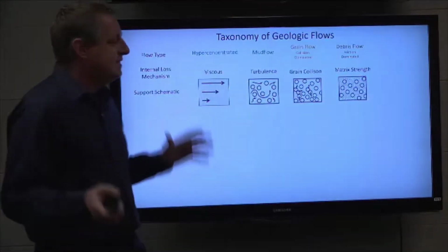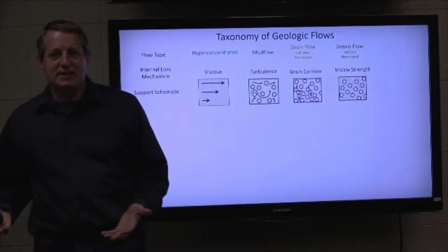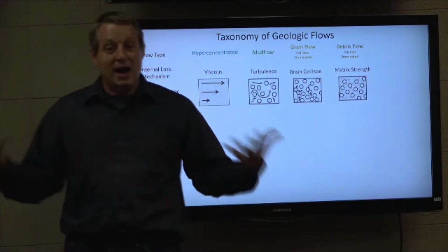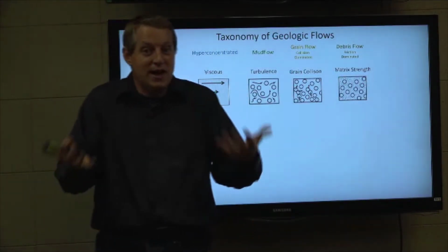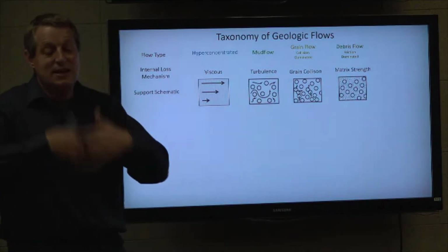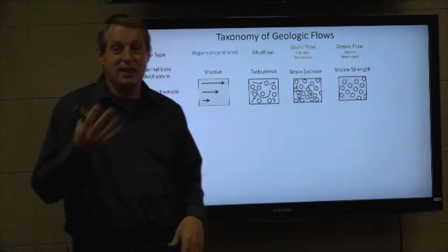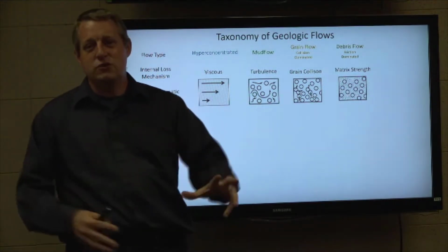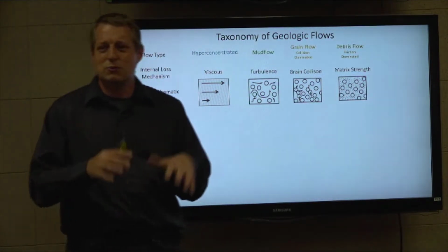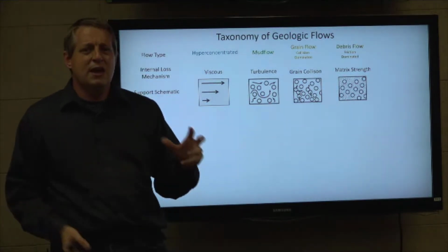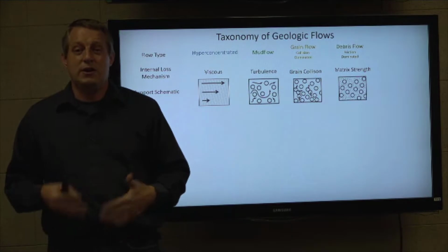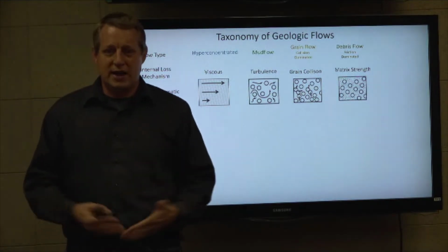And so here's the basic idea: most alluvial flows that we deal with carry sediment. That's why I have a job, right? And these sediment flows can be really high, like a dam removal can have really high sediment loads. A reservoir flush can introduce a lot of sediment into the river. But even with those, what we would consider extreme events, the volumetric concentration of sediment in the water is still generally low enough that the particles don't interact meaningfully.